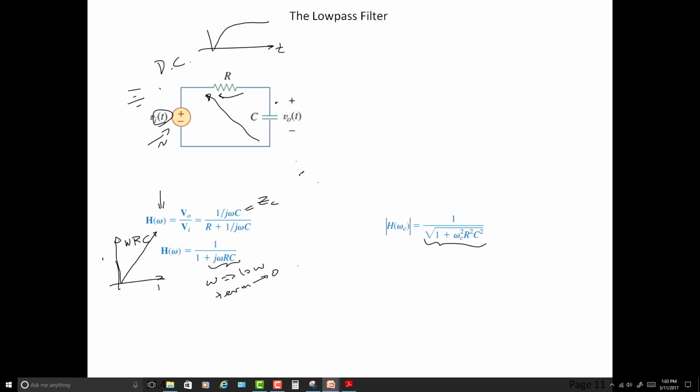And you can just see as this line gets longer with increasing frequency, this magnitude gets longer, and the phase angle approaches 90 degrees. So you can kind of see, just watching it, drawing some vector pictures, how this is all going to go here. All right. So the cutoff, or the corner frequency, I used cutoff because there's only one point going on.